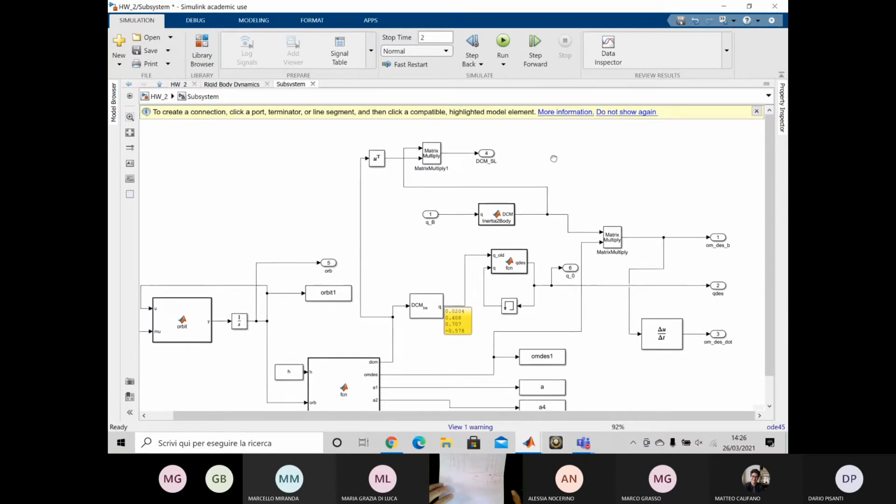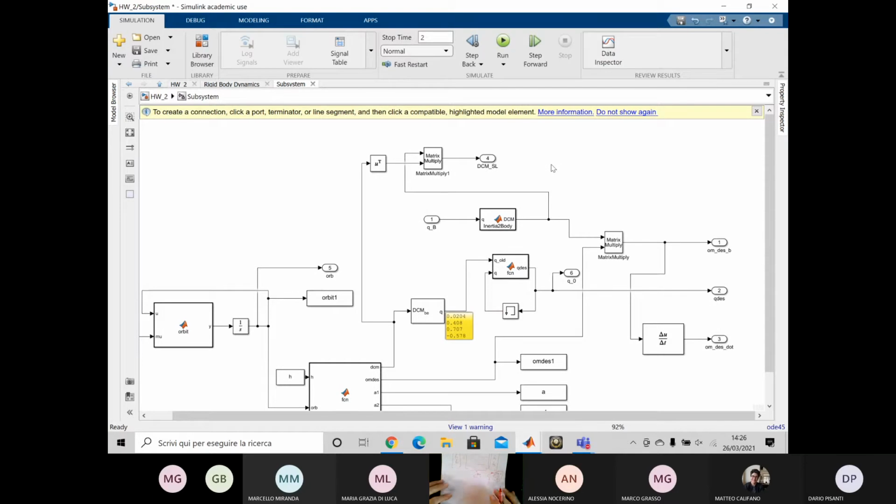And so my sanity check usually, I'll admit I'm really terrible with rotational matrices. I always make the mistake and I end up transposing. So I'm telling you right away. But my check is usually, if I want to make sure that what I'm obtaining here is the one that goes from A to N, the DCM should allow me to take a vector V expressed in A, put the DCM in front of it, and it should give me the vector in N. So these are the checks that you may want to perform before you say, okay, this is the correct matrix or I have to transpose it. I think this makes a little more sense now.